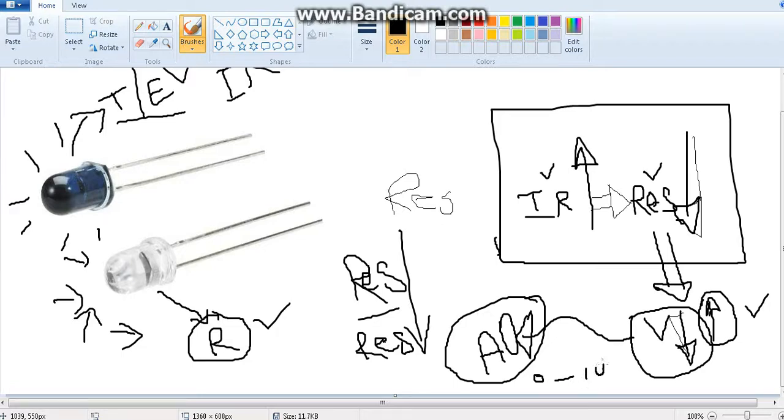If the voltage is falling down, the analog value will also fall down. We are only reading the voltage using the analog input. If there are few IR rays and resistance is high, the analog value will be a higher value.